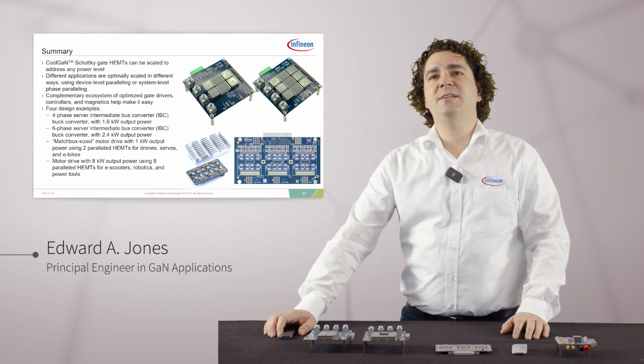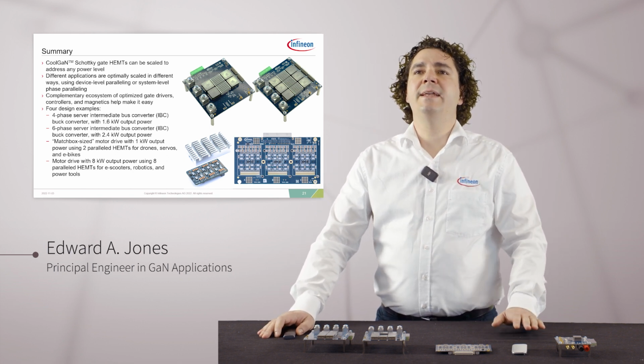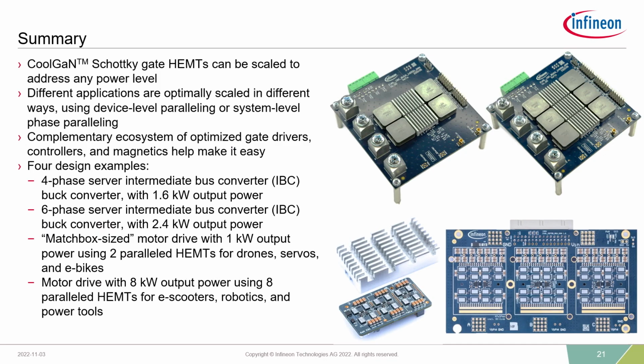So in conclusion, I just want you all to understand that the CoolGaN Schottky Gate HEMT in a half bridge can be scaled to any power level that you need to address. Different applications may require different approaches to scaling different power levels. You might want to parallel devices, especially in applications like motor drives. But then when you have to think about other components like controllers and especially magnetics, it may make more sense to optimize for power density and efficiency by interleaving parallel phases.